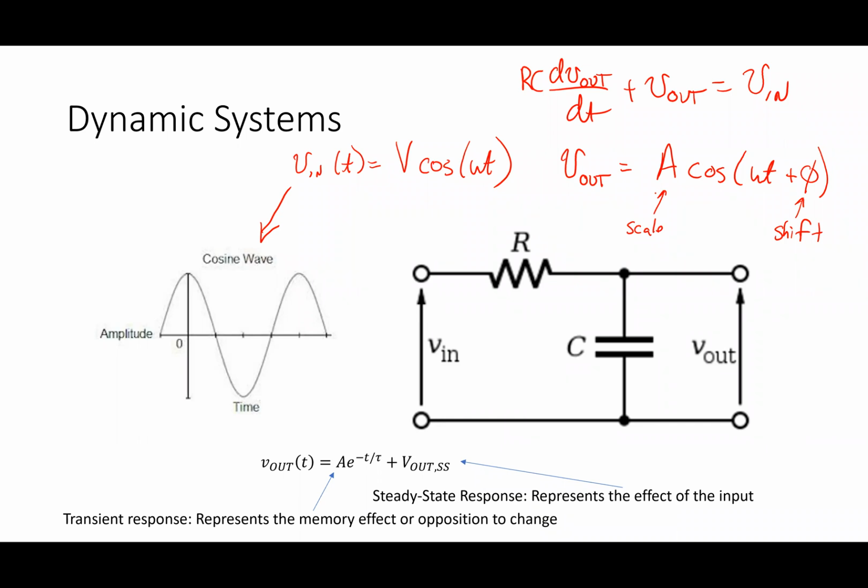So if this circuit right here had 2 resistors instead of a resistor and capacitor, it would not be a dynamic system. I'd turn on the power switch and the voltages and the currents everywhere would immediately get to their final value. But once I have a capacitor, the capacitor fights the change. Same thing with an inductor, it fights the change. So with this, I have to write a differential equation. This is the differential equation we write. We could get that from KVL.